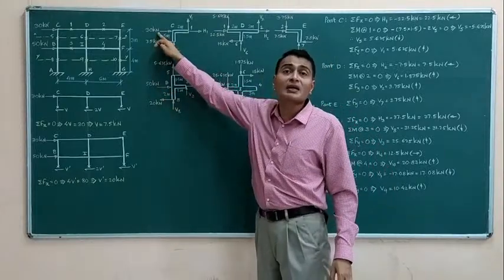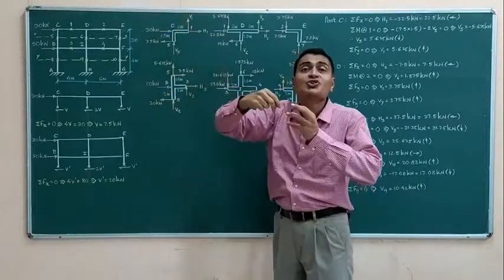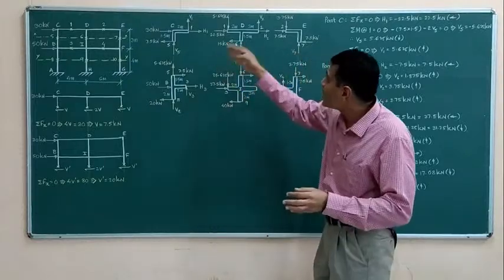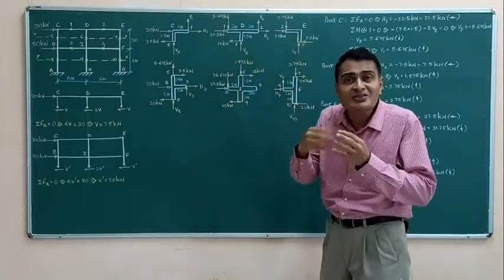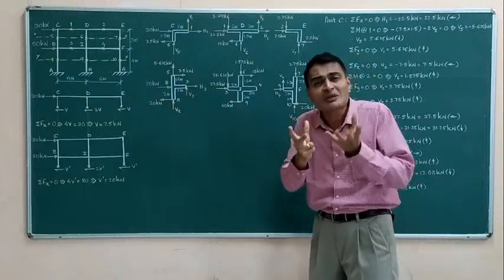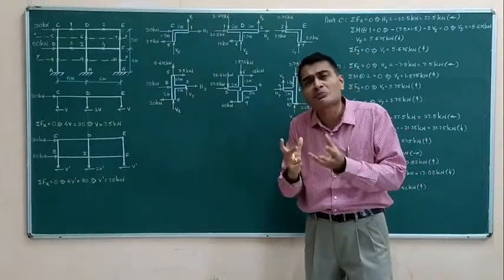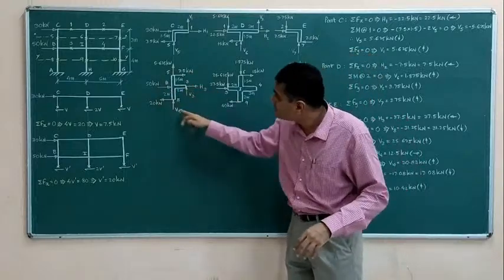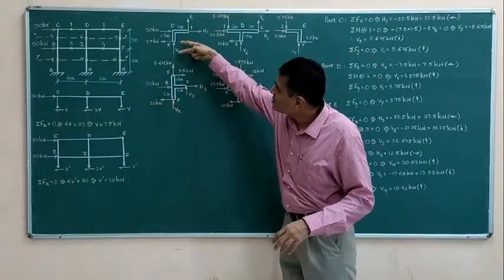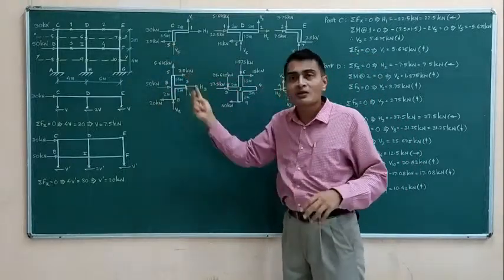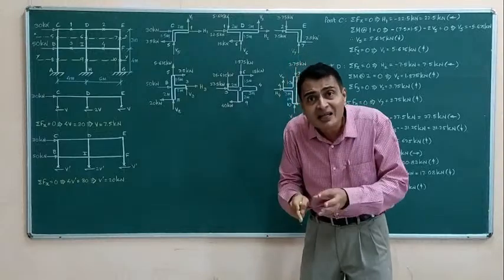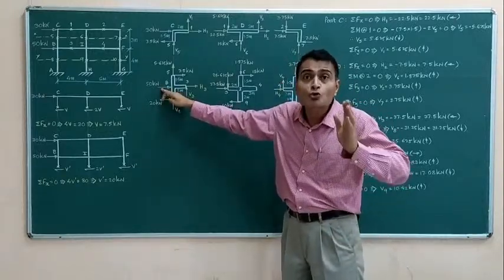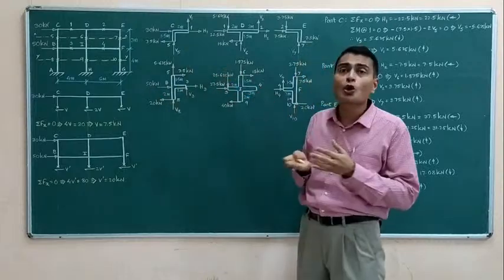This you won't forget because this is the drawing with which you start. So you are very alert at the beginning. And then as you develop many FBDs and you get engrossed in the equations and calculations and terms, this is a lot of work actually. So when you develop this FBD, in the course of that give and take, you simply forget to consider the external load. Please don't do that because then your answers will all go wrong.